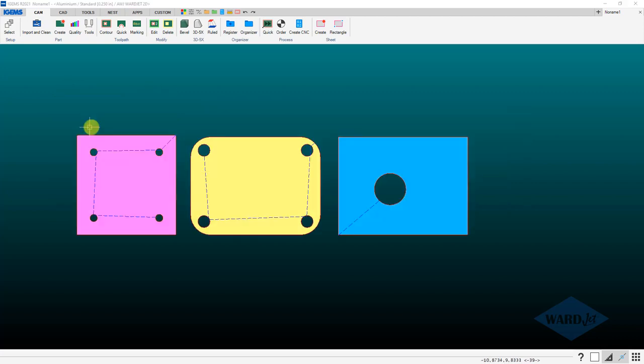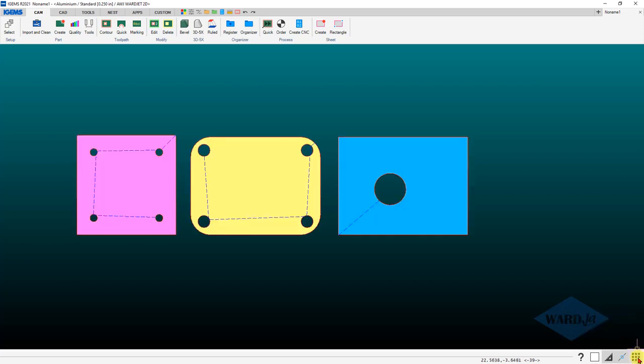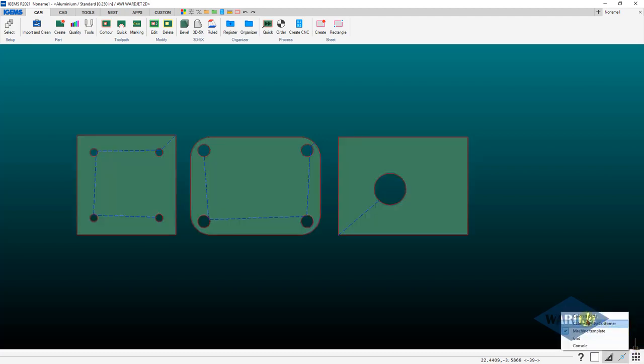Also note that if you want to toggle between colored and the traditional green color, lower right hand corner you've got this button with the 9 boxes on there. Click on here, and then you have this toggle here to switch between the traditional green and colored. So if you've got an older file that you made and they weren't colored parts and you want to colorize them, you can use that toggle button there.